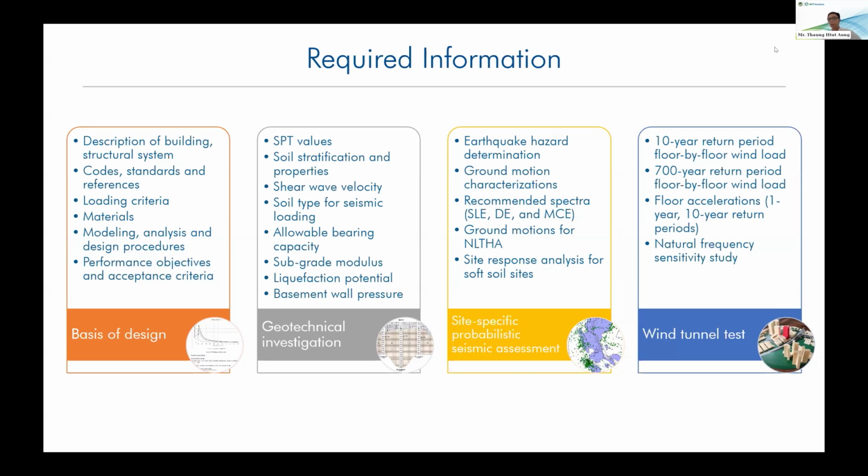For tall buildings, wind tunnel testing is also important. We have to engage the wind tunnel consultant to carry out the structural load study. For ultimate strength design, normally we use the 700-year return period wind load. And for the serviceability check, we use the 10-year return period wind load. The wind tunnel consultant will provide us the floor-by-floor wind loads for service level and ultimate strength design.